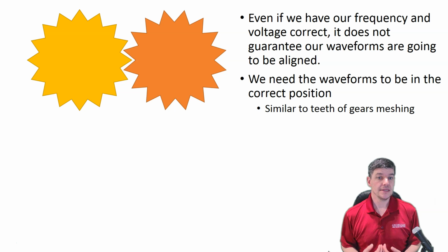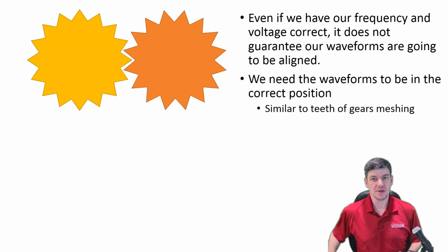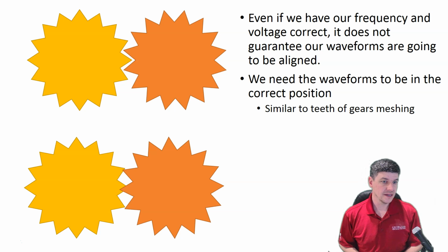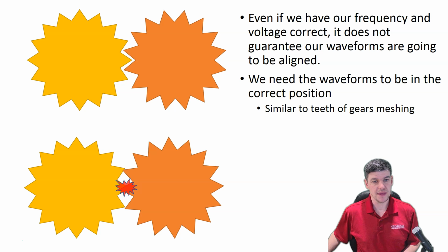Okay. And not only those things, but we also have to be considerate about what is the position of the teeth, or what is the arrangement of the waveform. So if I try to connect my gears together and the teeth weren't in the right position, then I'm going to create a problem. So we have to avoid that.